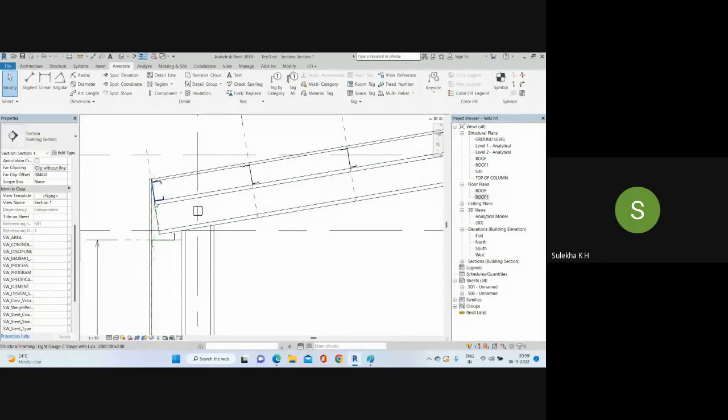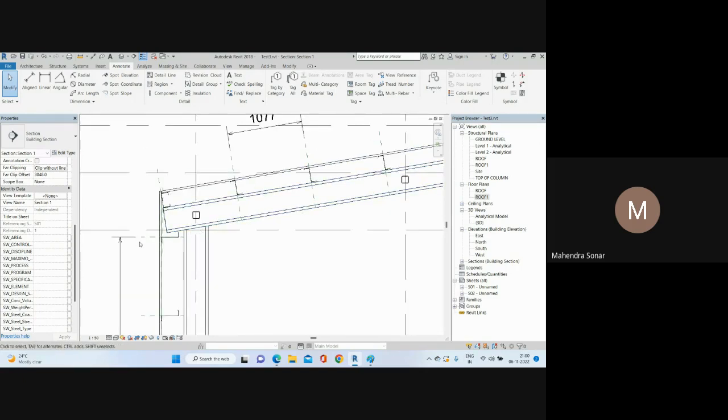That means on the basis of this calculation only we need to fix the grids exactly in the beginning, right? Exactly. So it's whatever you have designed. All the design inputs are your inputs for creating the model. So you need to fix your design first: what is the overhang, which connection you want to give, moment connection or any connection as per your requirement. On the basis of that, you need to fix all the grids and all overhang, all those stuffs.